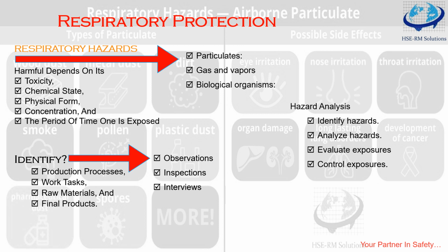Now, here I would like to discuss one more aspect, that is assigned protection factor, APF. Assigned protection factor means the workplace level of respiratory protection that a respirator or a class of respirators is expected to provide to employees when implementing a continuing, effective respiratory protection program.